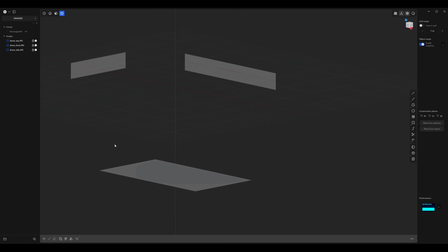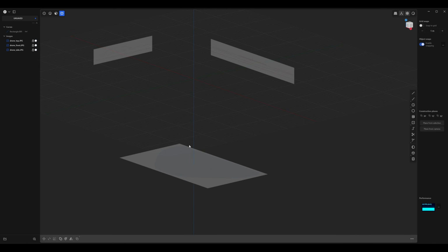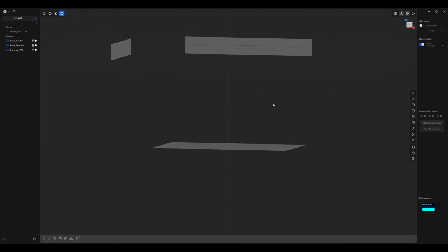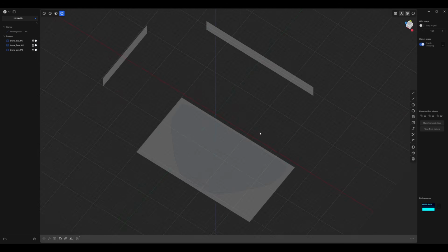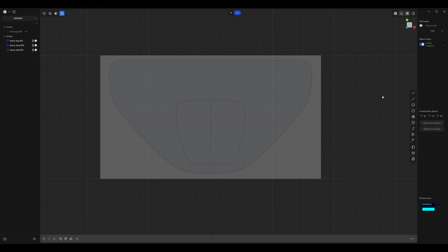And now you can go ahead and move around and you will not be able to click on them, which is what we want. So now we can start building our spline cage, which is what you usually want to do when you're building complex surfaces or vehicles that have organic forms. Let's start by going to the top view, and then let's select our control point curve over here. Click down and make sure you select the one that says control point curve. And we're going to trace half of this model so that we can then mirror it over.